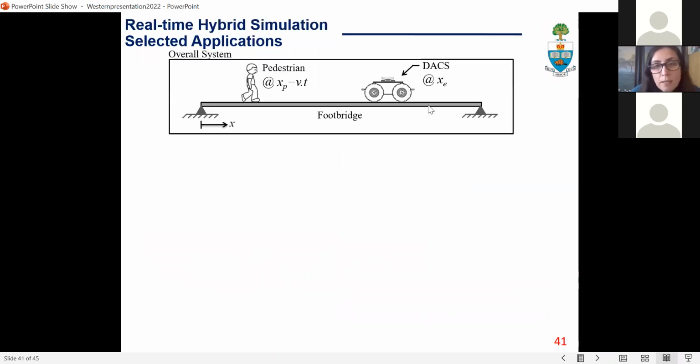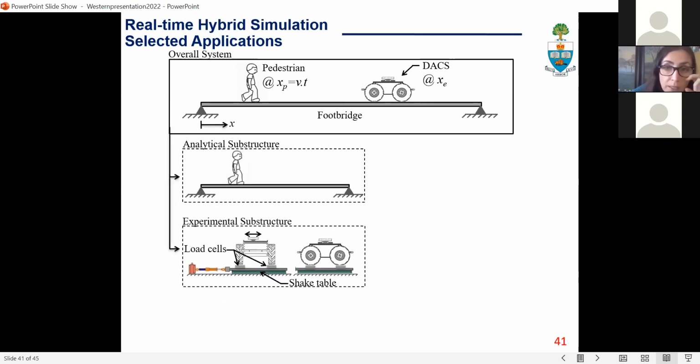And the idea is when we have a lightweight footbridge, pedestrian bridge that is vibrating, we can deploy one of these devices. It can sense the mode of vibration. It can calculate the optimum location using its sensor and robotic platform. It can go to the optimal location and then activate the active mass damper to introduce optimal control force to control the vibration.